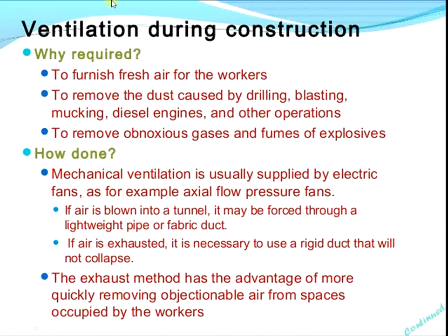In this mechanical ventilation, if the air is blown into the tunnel, it may be forced through a lightweight pipe or fabric duct. And if the air in the tunnel needs to be exhausted, then it is necessary to use a rigid duct that will not collapse.